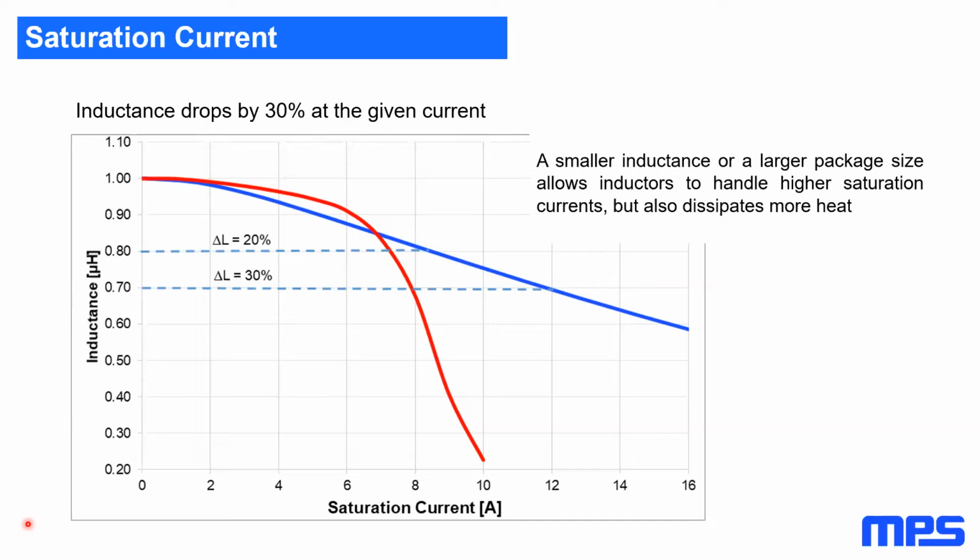We will have at the beginning constant losses. This is when we are starting the measurement. Then we have the switching losses, which are more related to the core losses. And then at the end, we have the copper losses. And again, this is the same shape, same kind of component. And these are the real results with the same board, with the same component.